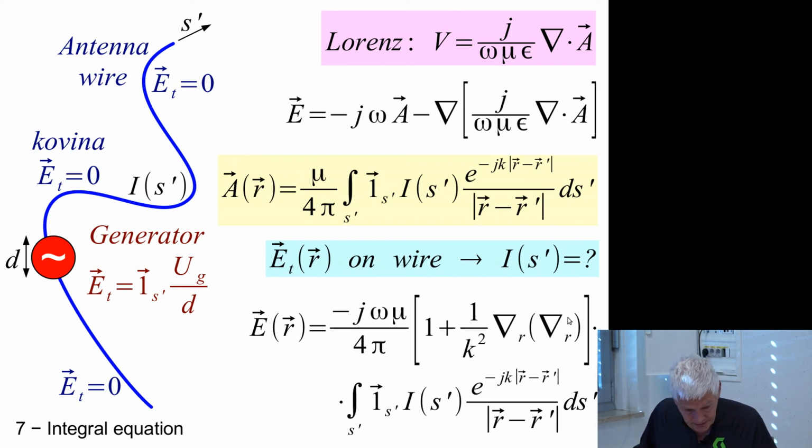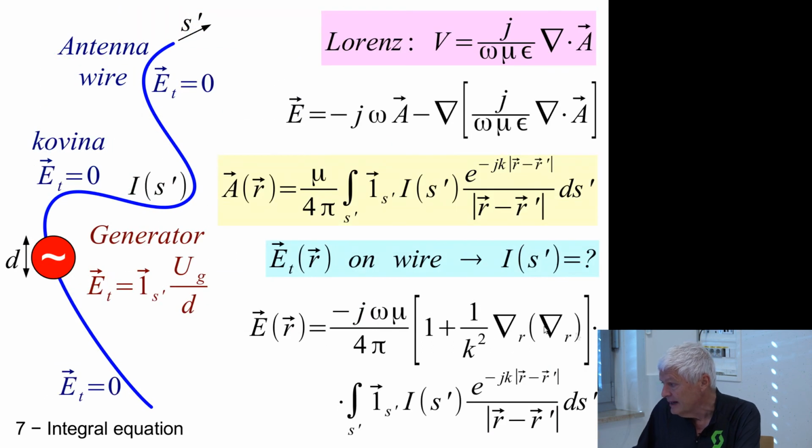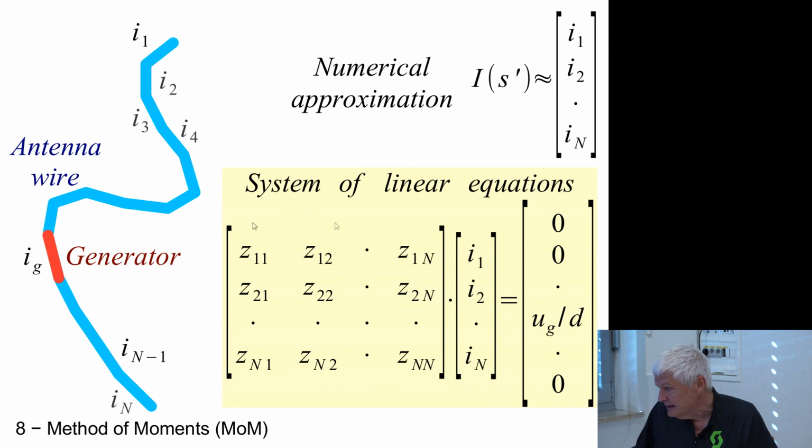So if I have a sinusoidal current distribution, exactly sine of kz or ks here, where k is the wave number, then this thing has an analytic solution, and at least calculating our matrix is not that difficult. It's still time consuming numerically on a computer, but it is straightforward. We do not need to perform numerical calculations here. We just calculate analytically each of the members here, and then we have to solve this system of equations.